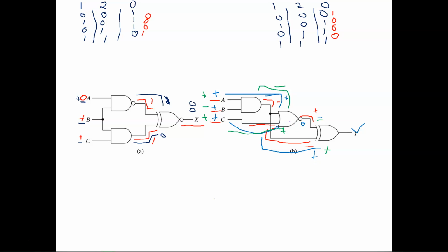So that's why we end up with this guy, he's actually inverting the signal. So if he goes positive, you better make sure that whatever's trying to balance it out is what? You need to make sure whatever's coming out the other end is negative, and vice versa. And that way you can get a signal out.